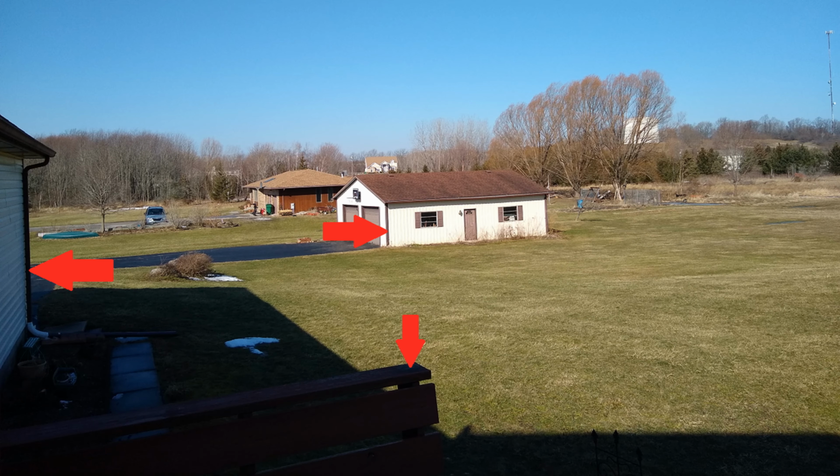The barn is more than 100 feet from the front of the garage. The barn feeder starts at the southeast corner of the cellar. It exits the northwest corner of the cellar, right under where I'm standing on the deck, in this picture. So I'm guesstimating it's over 175 feet long, maybe close to 200 feet. The entire feeder was run with number 2 aluminum.